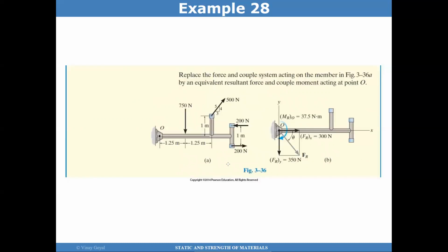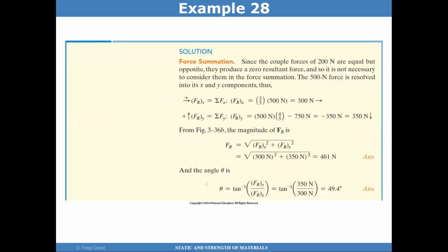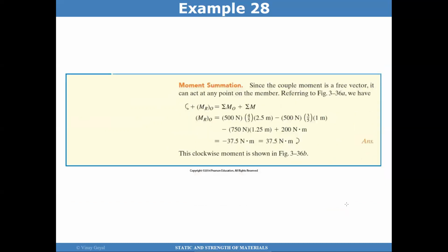And that's exactly what we've done. So decompose this force into the X and Y direction, and then sum all the forces in the X direction, all the forces in the Y direction. And then once you do that, you can calculate the magnitude of the force and then the angle, how that force is acting. And then calculate the moment should be a fairly straightforward approach.